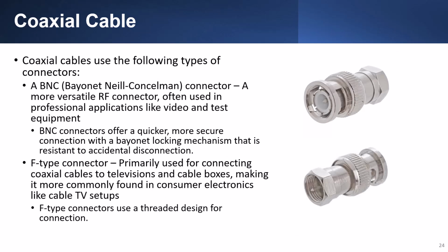Coaxial cable uses the following types of connectors. The bayonet Neill-Concelman, or BNC connector, is a more versatile RF connector, often used in professional applications like video and test equipment. BNC connectors offer a quicker, more secure connection with a bayonet locking mechanism that is resistant to accidental disconnection.